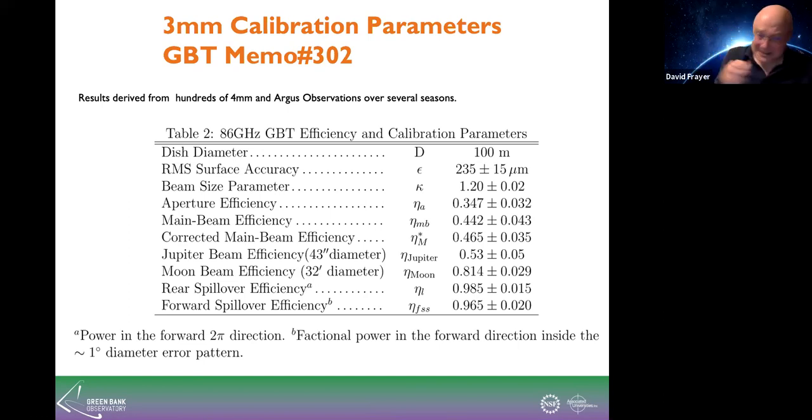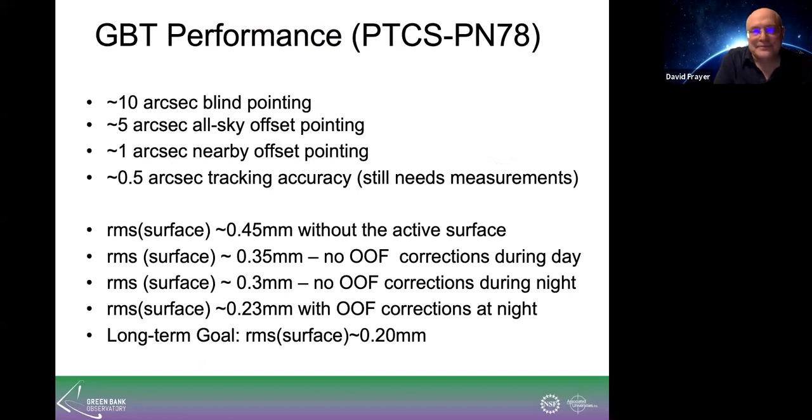So typically you don't have that with radio telescopes. They're not nearly this thin. This is because of the unblocked aperture. So if you point to a point on the sky, roughly about 95% of the antenna power is within 1 degree of where you point, which is quite spectacular. That's at higher frequency. The beam is bigger, it expands a bit.